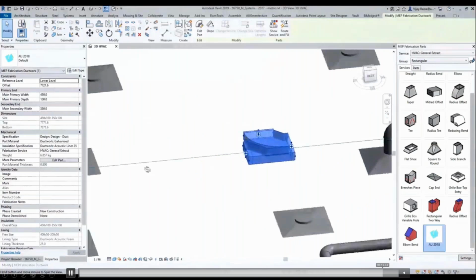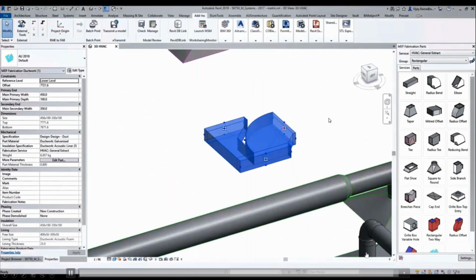You can use those kinds of fittings. So this is the workflow of using our fabrication design to fabrication. These are the solutions that can be used: starting from Revit, go to fabrication estimation to estimate your ductwork. In CADmep, if you want to create additional hangers or supports or additional duct branches, extra services you want to work on, you can create it. And then you can take it to CAMDuct for the manufacturing.